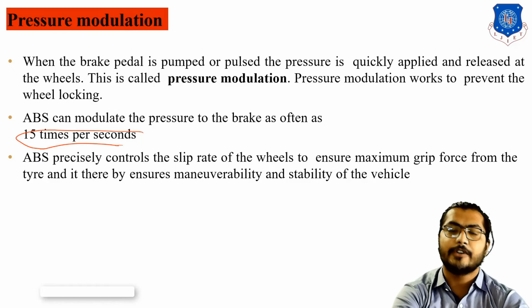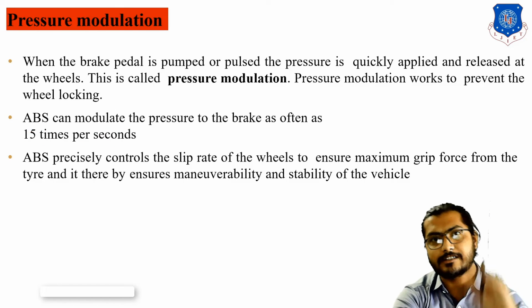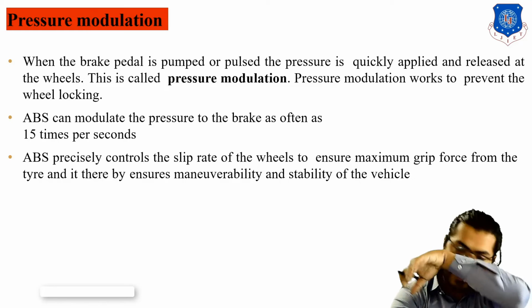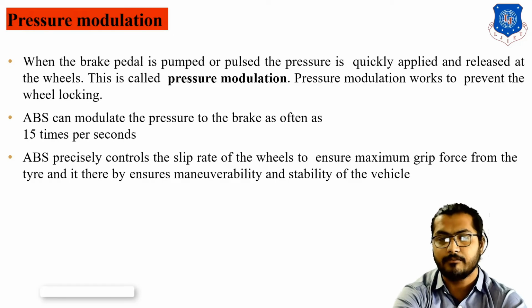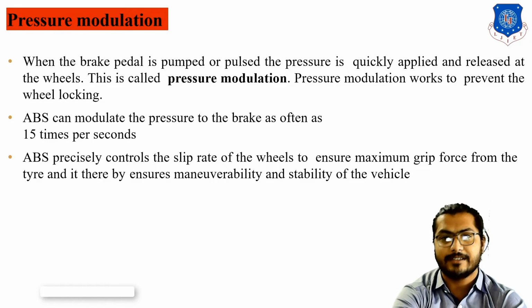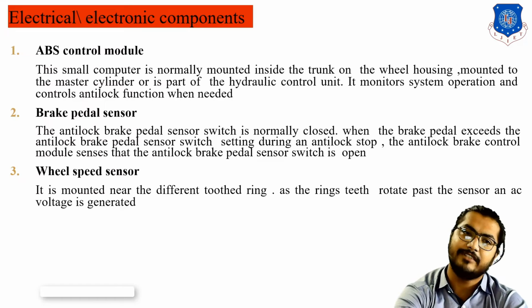ABS is precisely controlled by slip rate. Okay, it controls the slip rate, so your vehicle will not be slipping and you can control your steering very easily, ensuring the maximum gripping force from the tire. It also ensures the maneuverability, or you can say the turning and stability, of the vehicle.